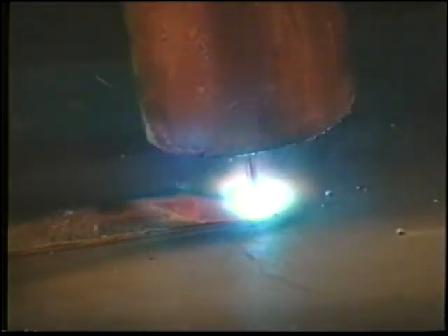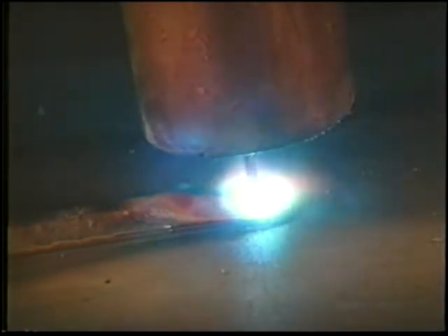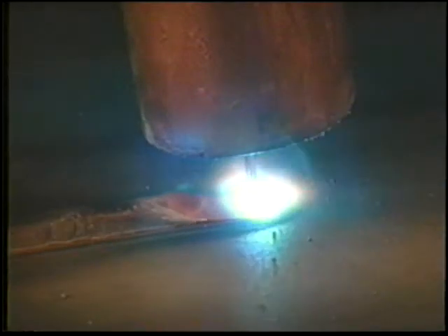Short-circuiting is a common type of metal transfer used in the continuous wire process. In the short-circuiting mode, all metal transfer occurs when the electrode is in contact with the molten puddle on the workpiece. Because the arc is not continuously on during the short-circuit transfer, the heat input is lower than other modes. This fact limits its use for heavier sections but makes the process ideal for joining thinner metals. Also, the intermittent cooling of the puddle provides for good control in out-of-position joints.